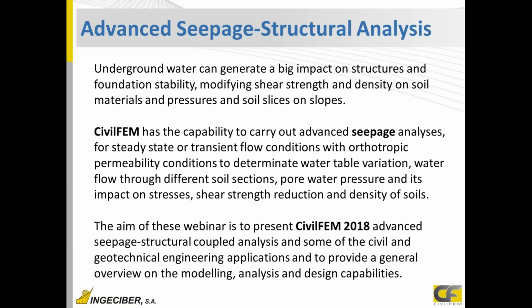With CivilFEM, we can perform advanced seepage analysis, and not only steady state, also transient, with orthotropic permeability conditions in the materials, to determine water table variation, water flow through different soil sections, pore water pressure, and also, very important, the impact of this pore water pressure on the stresses in the model, to work with effective stresses in the geotechnical materials, and how these pore water pressures affect the strength reduction of the materials, the density of the soils as well, and the impact that can have on the stability of the foundations and of the structure.